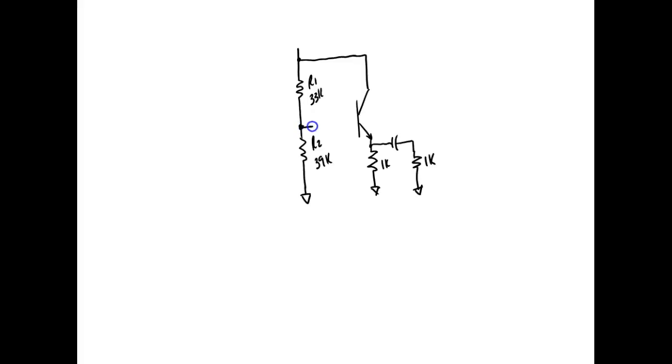And then we have, oops, missed my center, but that's okay. And then we're going to put our signal generator right here. We're putting in 3 volts peak to peak. Why? Because our signal generator won't even put out 2 volts. And then VCC is equal to plus 10 volts.